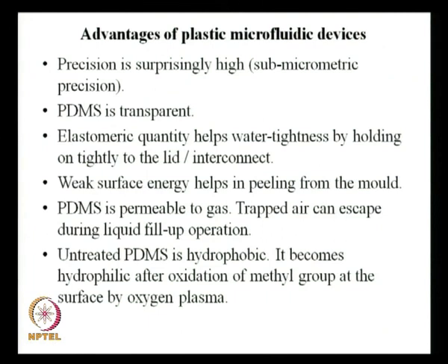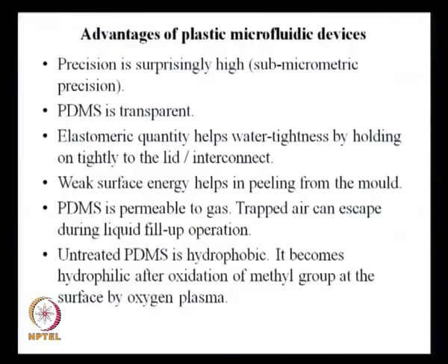The oxidation takes place on the methyl group at the surface and PDMS becomes hydrophilic. This kind of property change may not be very easy for silicon and other materials, but plastic has this property. You can change the property of a plastic material very easily by such surface treatment. So that is one major advantage of plastic devices. These are some of the advantages that I have listed here.